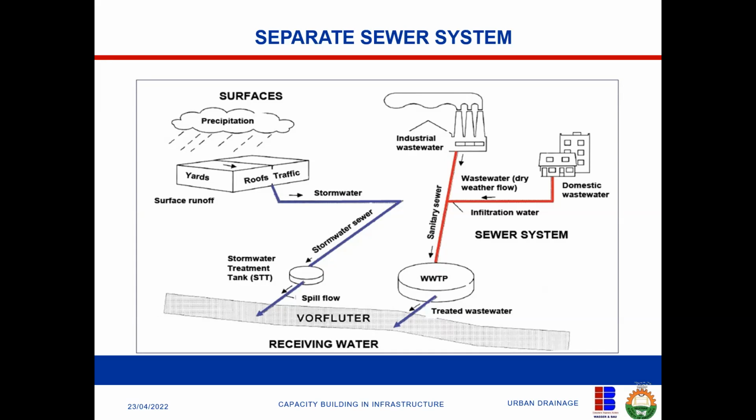So when it's raining, they will have food or wastewater coming that, instead of providing food for the bacteria, will come and distort the hydraulic balance. Or sometimes it will even come and wash out the bacteria that they have built over the years, over the months. Meaning that they have to start all over again to build the culture. So what they do is that they will open their bypass.